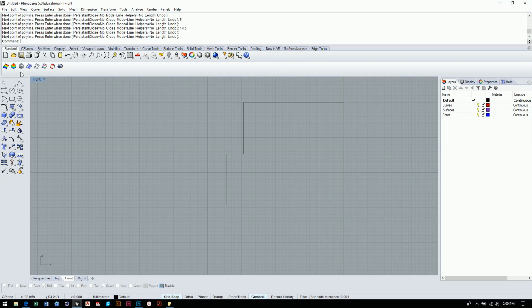And then what I'll do is I'm going to set a line a certain distance over from the center line here, and it's going to be a 7.4 millimeter line, and it's going to be about 26 millimeters over from the z-axis.